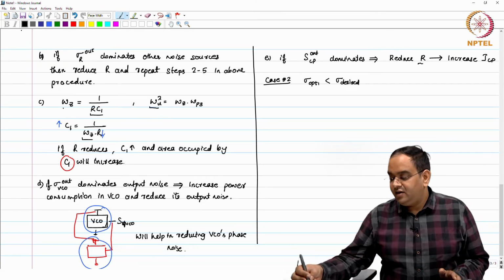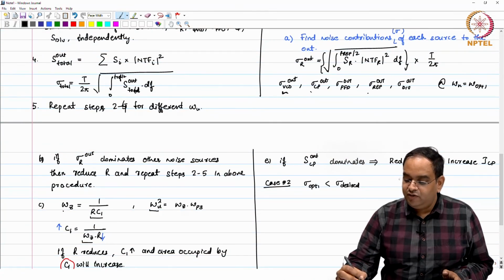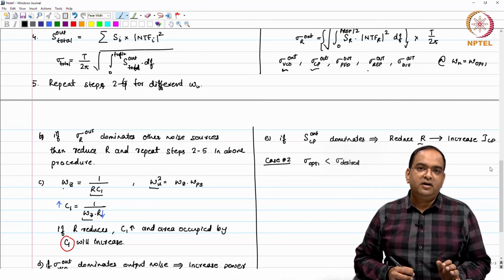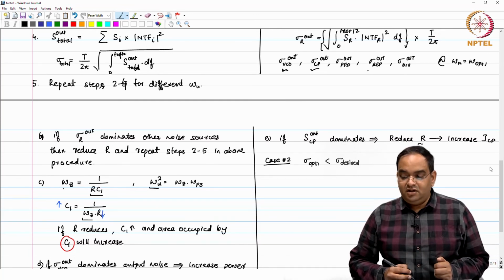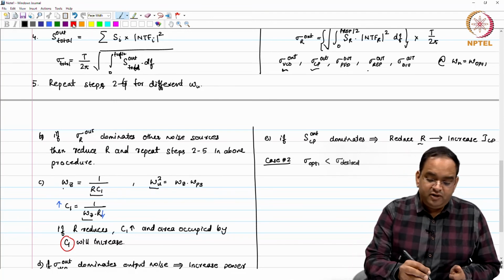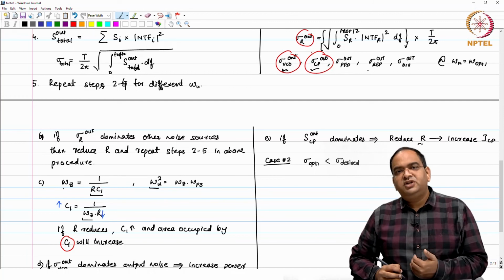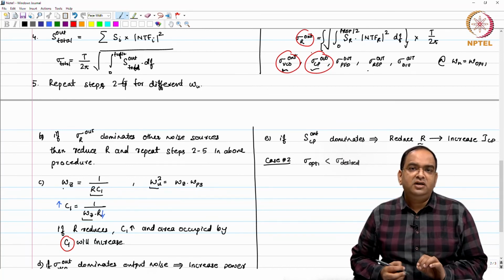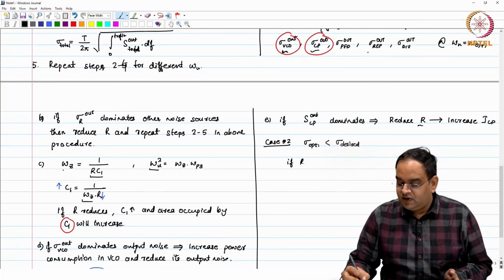Okay. So, in that way you can go ahead and find out, sigma VCO and all those things, you find here which of these noise sources is least dominant. So, reference is coming from outside, you have divider, you have your PFD, charge pump and so on. Once you find which is least dominant, mostly it will be either your R or VCO or charge pump plus PFD. So, you find which one is least dominant, and based on that you reduce the power consumption in the design.